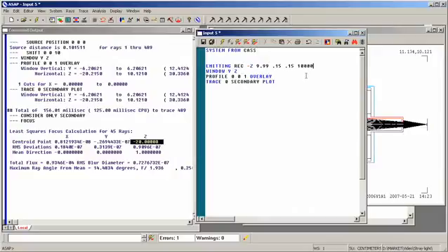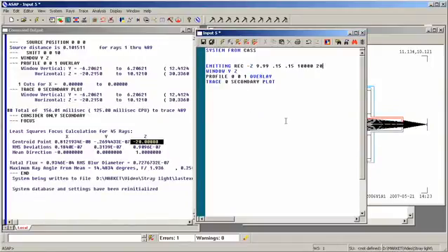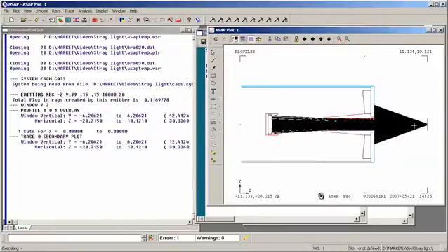We'll say 10,000. And we're going to confine those rays to a 20-degree angle just to make the ray trace more efficient. We issue the end command telling ASAP I'm done with my previous work, and go ahead and execute this file. Here's our backward ray trace.